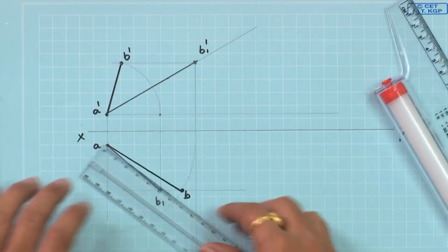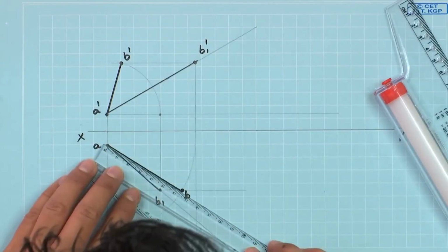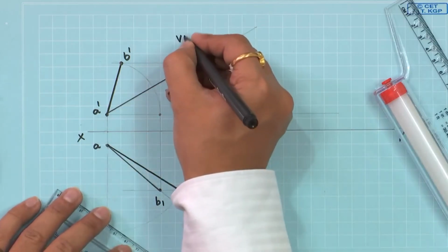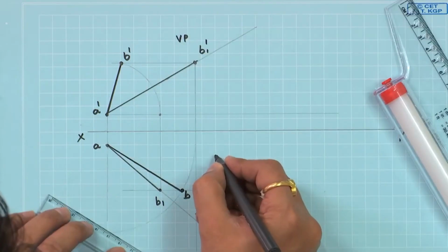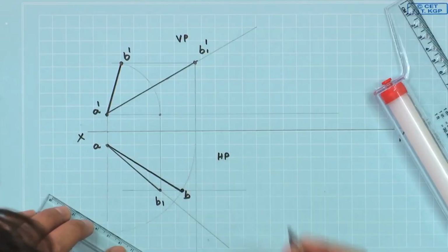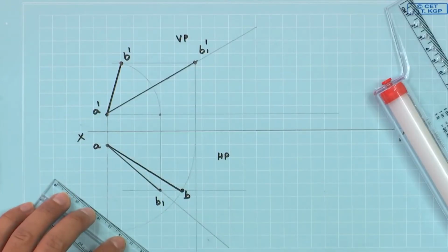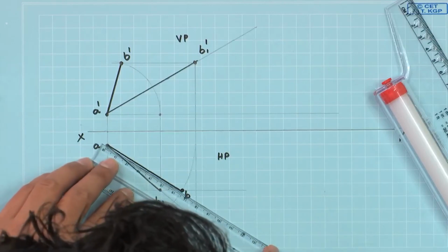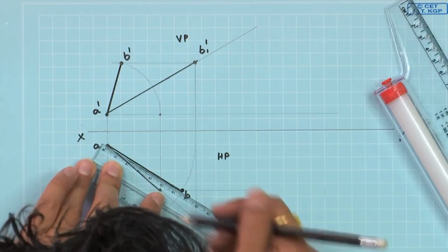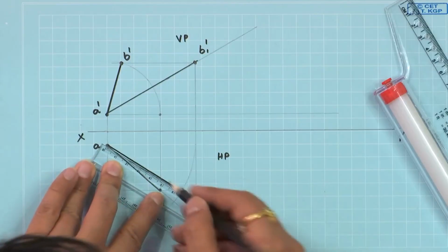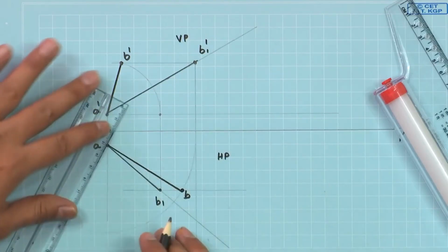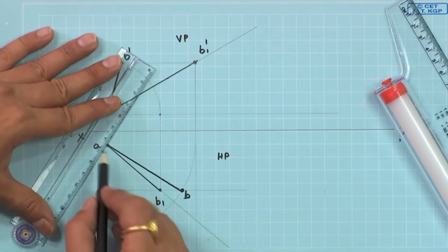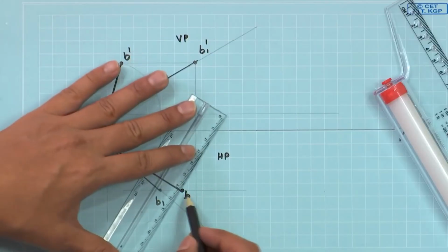And let us find what those lengths are. So, the projection lengths, let us note them down. This is the vertical plane, this is the horizontal plane, and what we are interested in is the projected lengths, how much they are. If we measure that, it will be 64 units. So, 64 units we have to mark.